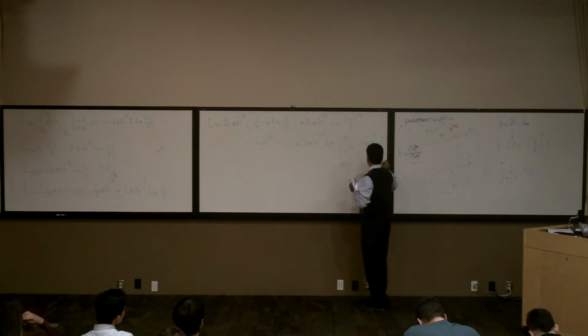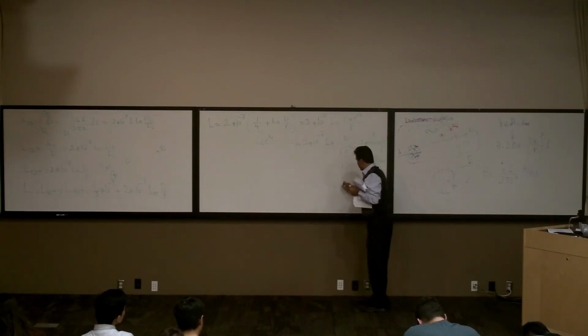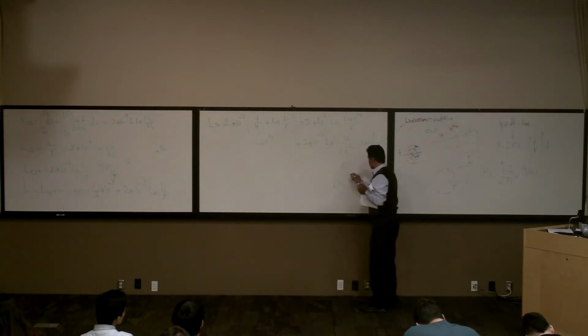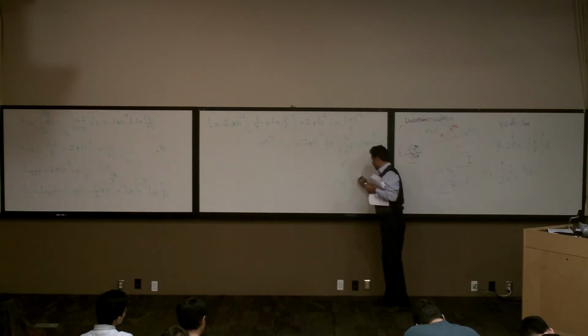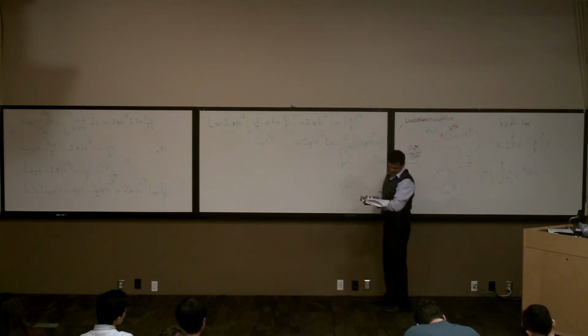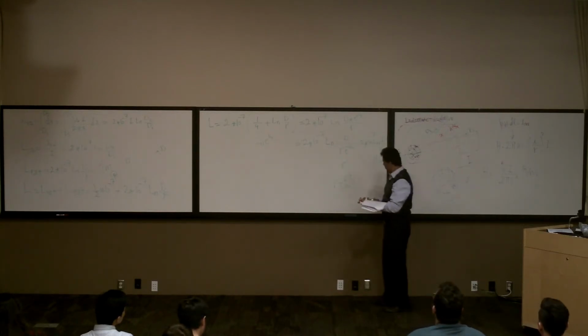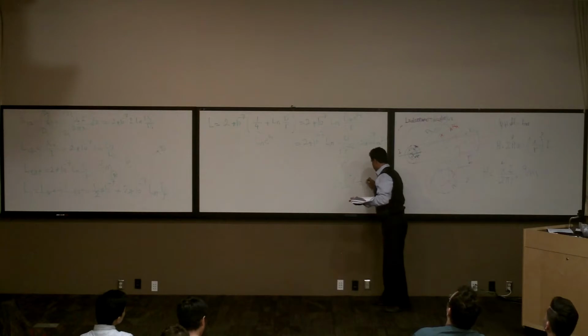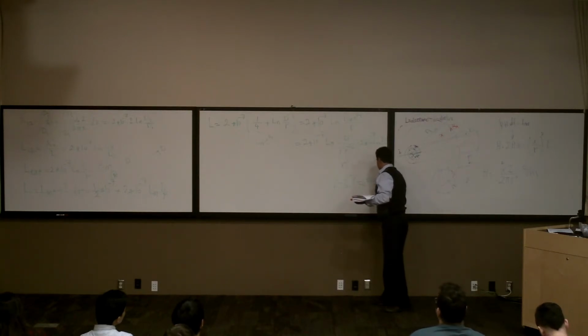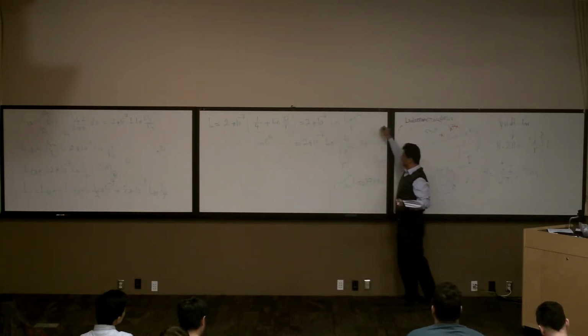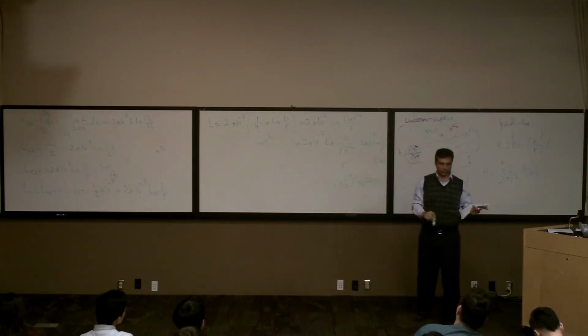Henry per meter. How much is the r prime? It is e to the power of minus 1 over 4 times r, and this number is 0.788, I believe, something like that. So basically this is 0.7788 R. This equation is the final equation. This is what you need to know.